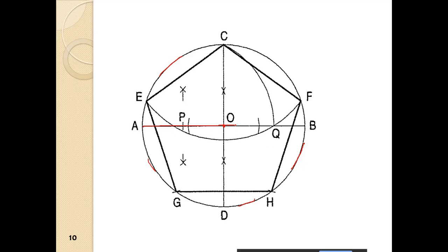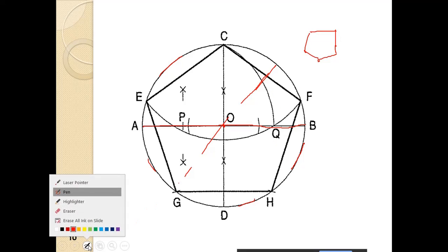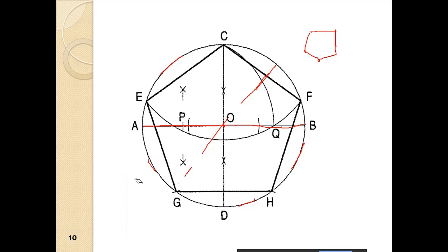then you draw the diameter in the direction that you want. So suppose you want the pentagon to point in a particular direction, suppose in this manner, then you have to orient the diameter in that way. So that particular diameter has to be in this manner. So the orientation will depend on what is the direction of this pentagon. So here once you have drawn the circle and the two diameters,